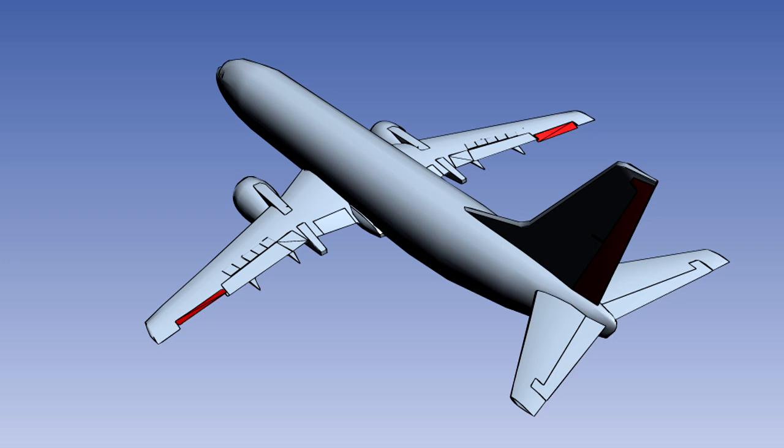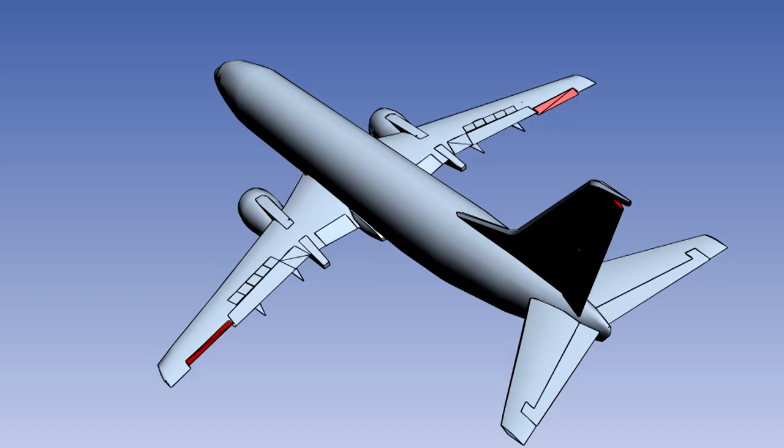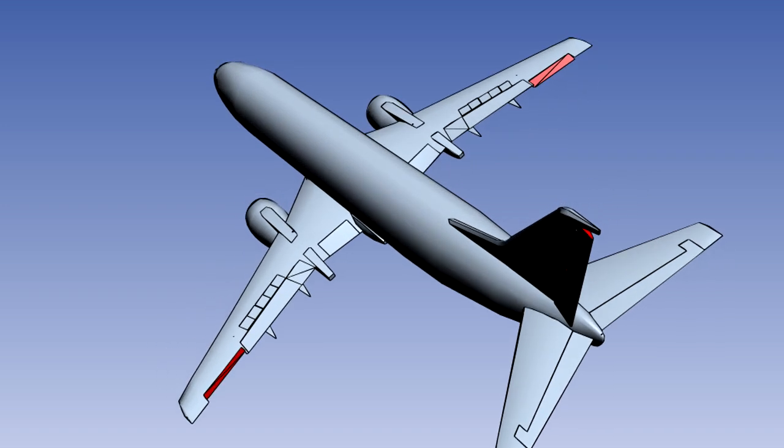In the aileron rudder coupling system, the aileron and rudder systems are interconnected, so that when the ailerons are deflected, the rudder automatically moves to counter the adverse yaw.